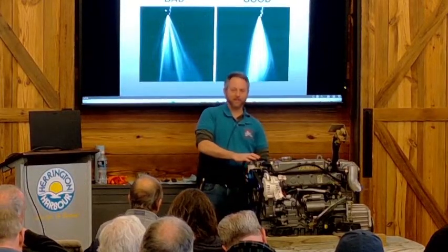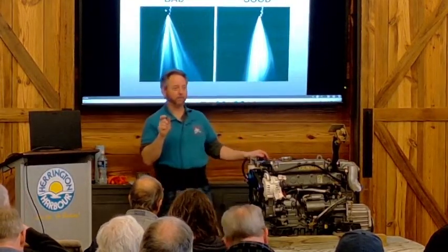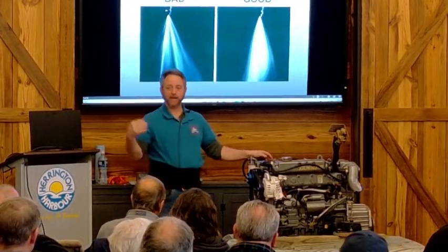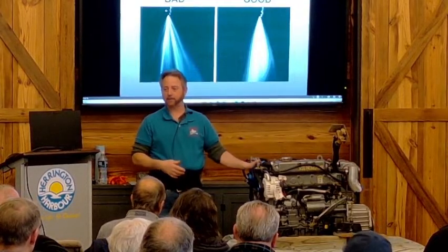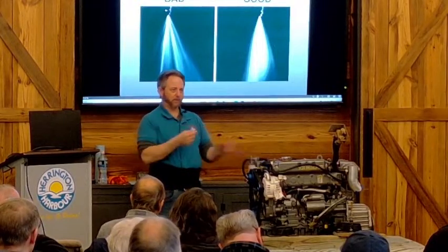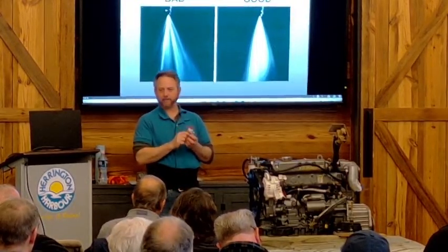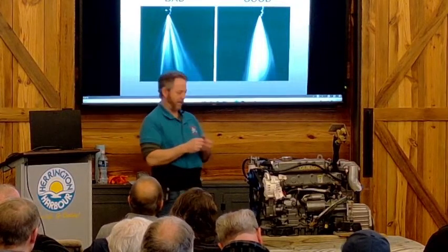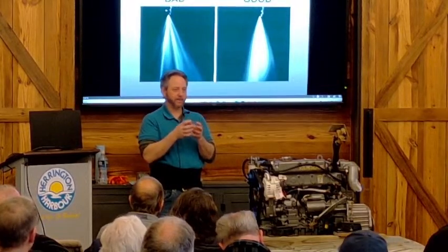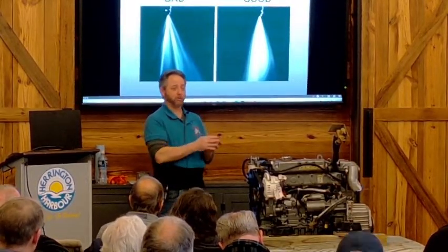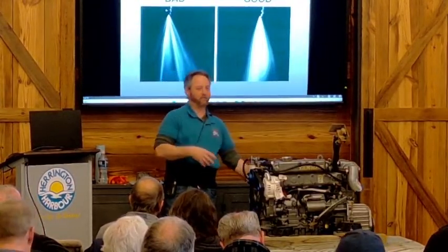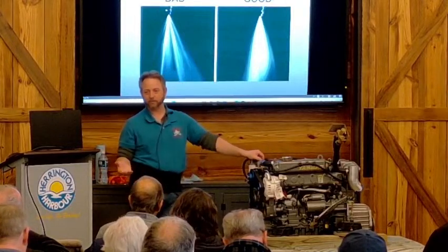There's something called a bypass valve built into every oil filter. If the filter clogs, this valve pops open and allows oil to continue to lubricate the engine even though the filter is clogged. Now when you buy an aftermarket filter, you don't know what the setting for that bypass valve is, because that oil filter from Napa might fit 200 to 300 different engines. Which one was it made to screw onto originally? So the only way to know that you've got the right setting is to buy the original equipment filter.